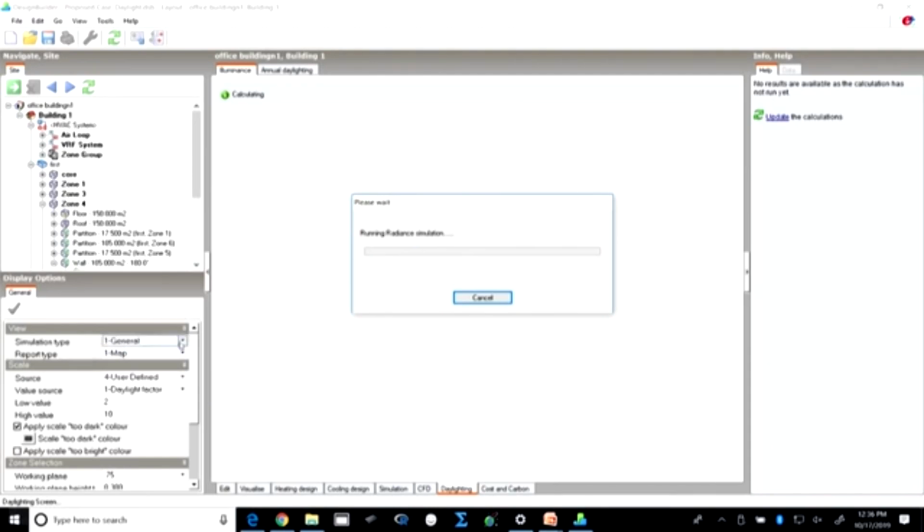We can also select, if we want to go for the compliance, either of these options, and it will automatically generate a report in the format which is desired for LEED or BREEAM or Green Star, and tell us whether this particular building plan and the fenestration design complies with the compliance criteria given in these rating systems or not, and we can see the changes.